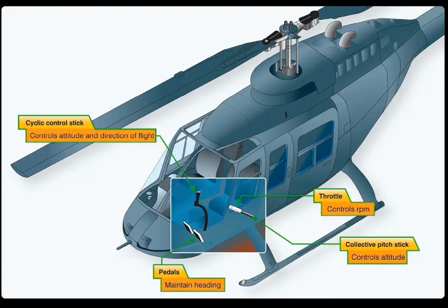How do wing flaps affect landing speeds and approach angle of an aircraft? Flaps increase lift of the wing, so speed can decrease without decreasing lift. Permits a steeper glide angle and lower speed for landing approach.